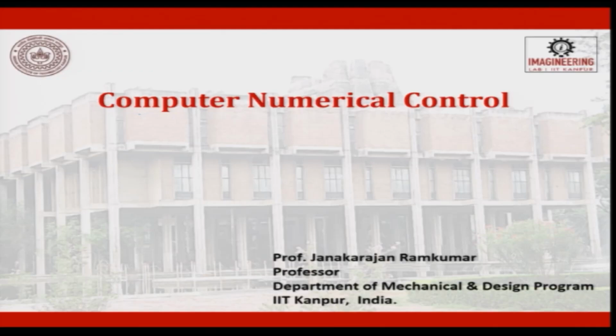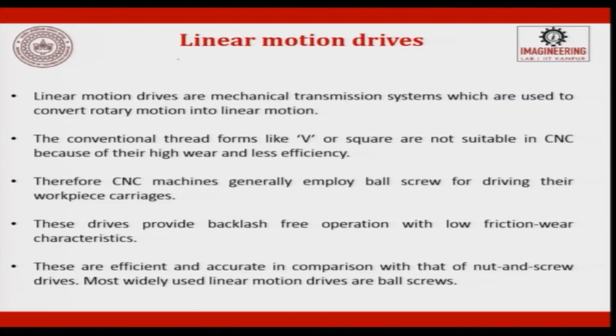So, welcome to the next lecture on computer numerical control. Let us move ahead with further discussion on the drives. Today we talk about linear motion drives. The linear motion drives are mechanical transmission systems which are used to convert rotary motion into linear motion. As I told you, a motor is moving a lead screw, which converts rotary motion into linear motion.